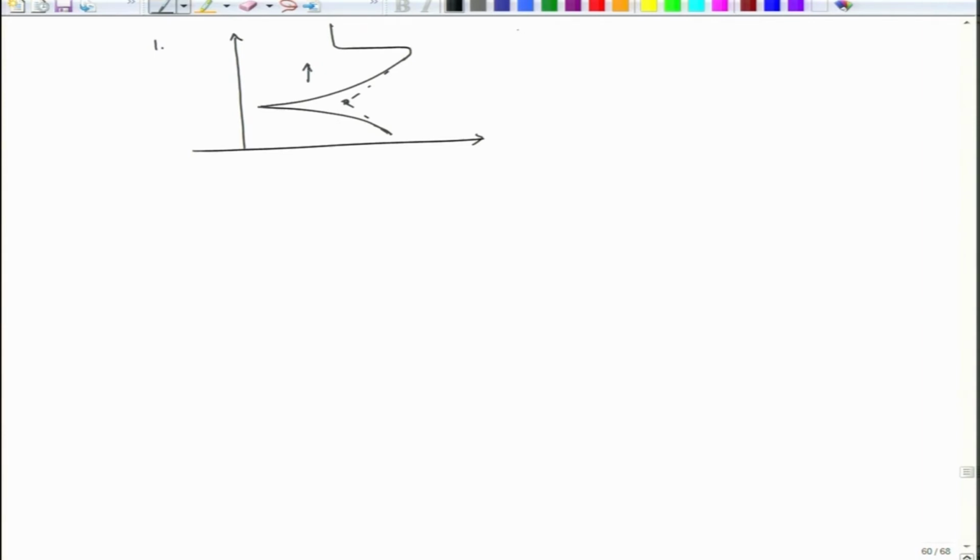Okay. So, when we do anodic polarization, this was the Ecorr. Now, in the free corrosion condition, the potential would be maintained at this level. When we take it forcefully to the positive, anodic side, the corrosion rate changes. As we go this way, the corrosion rate increases, reaching a maximum level, then decreases again and maintains a flat portion. So, this is corrosion rate with potential.